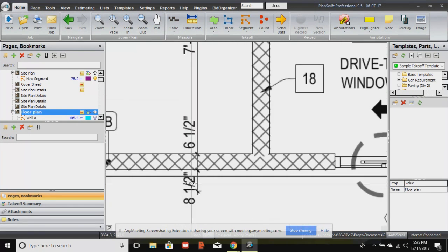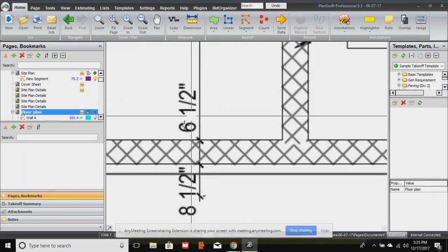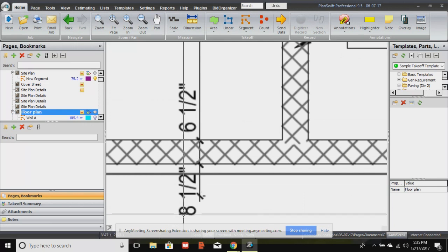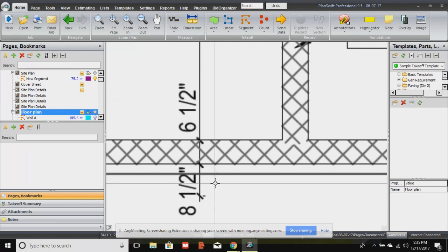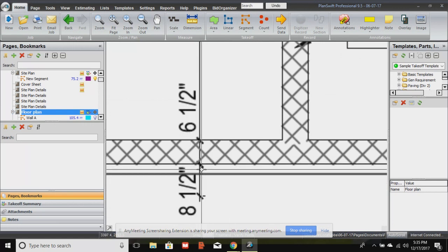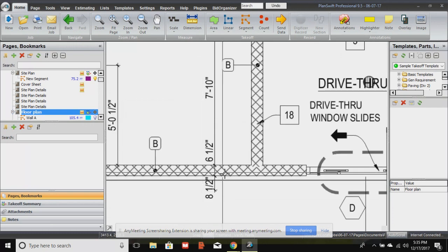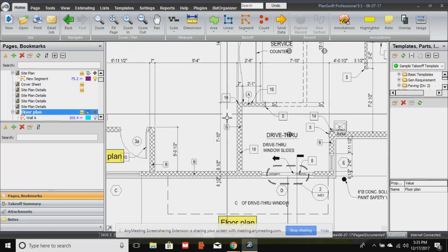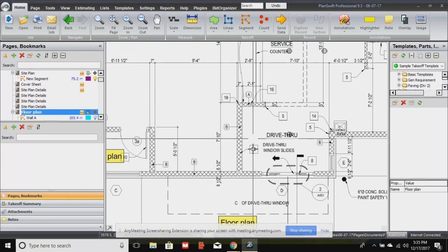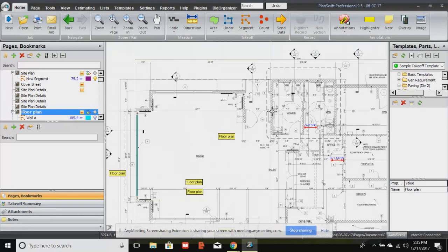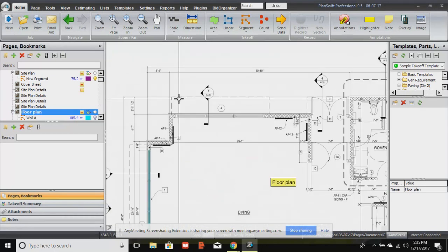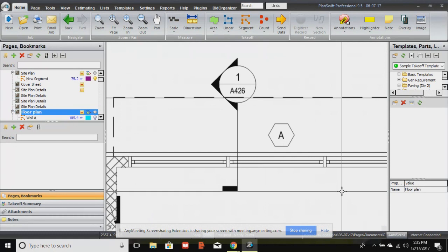Okay, so they're giving us another hash mark to hash mark, but this area right here is too small to fit that 6 1/2, and so that refers to that, and then that 8 1/2 inch refers to where they have the 1/2 inside of. Hash mark to hash mark, hash mark to hash mark, and you can reuse hash marks, and whatever number's in between is your actual length. Okay, so that's what you can use your floor plan for. We're still on our first view, plan view. Okay, so on our plan view, we have some symbols, and now it gets kind of hairy.